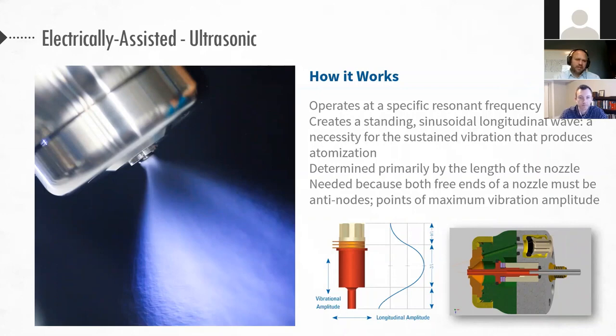And what's fascinating with these nozzles is you're able to get a very fine droplet with a tight distribution. And it's because of that piezoelectrics that's vibrating at a very high frequency. And that's what's giving you that primary breakup of that liquid. And you're going to see on our next slide kind of how fine that droplet is. And you can actually see it spraying in the lab.